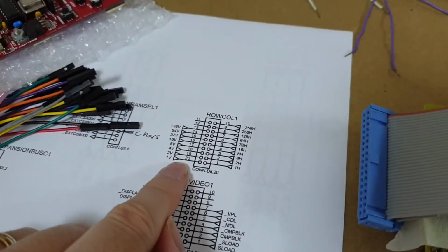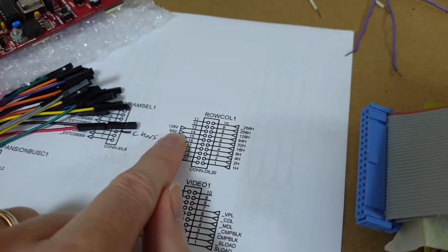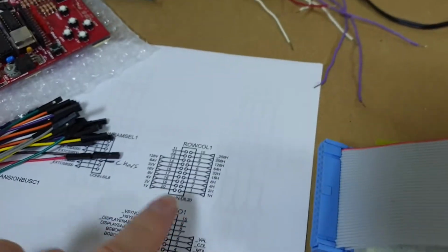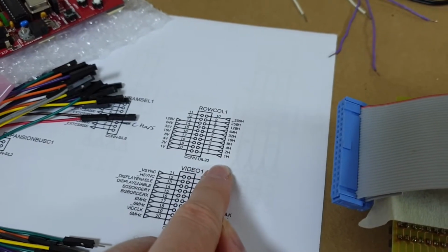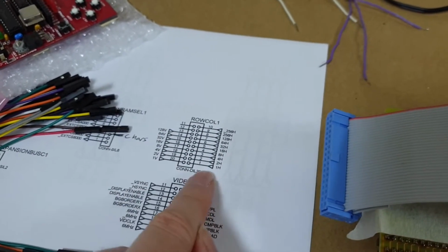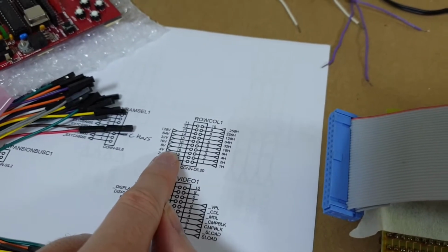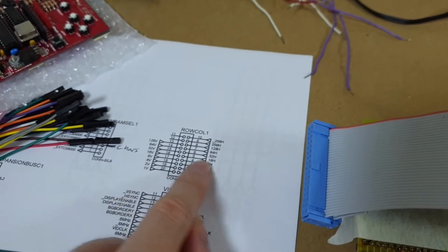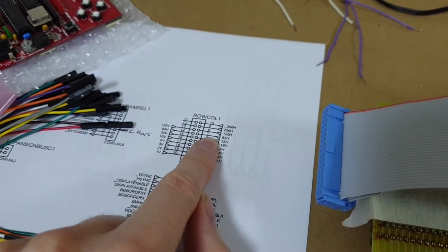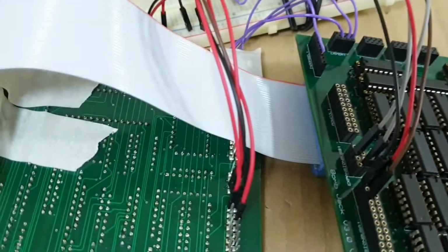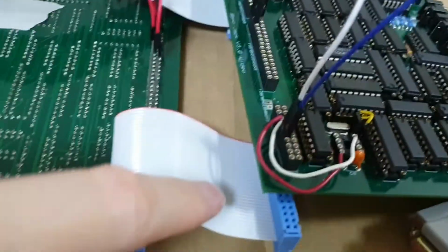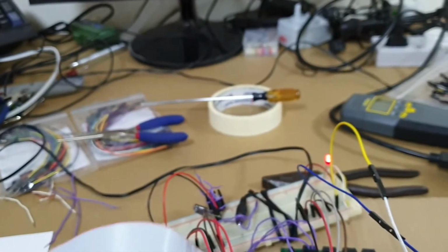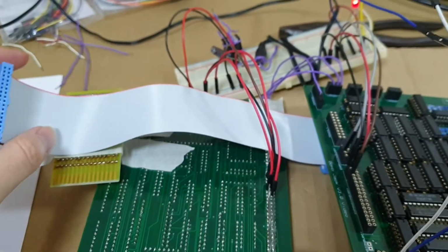So anyway, this side doesn't have very high frequency, relatively speaking. This side has the high frequency in there. So the high frequency pins, right? Engaging these and engaging these up to about here doesn't matter. But then when something across here engages, it just goes completely bonkers with a long cable. If I switch it back now so that the short cable is on the row column and then the long cable is on here, this tells me that maybe I should be a lot more economical with my cables between these boards. That's definitely worthy of note.